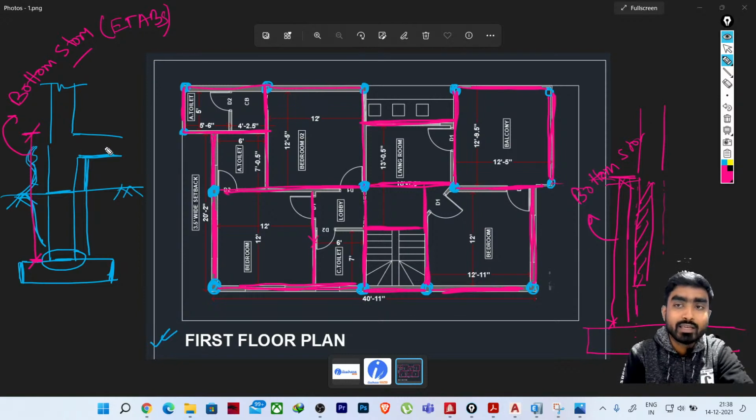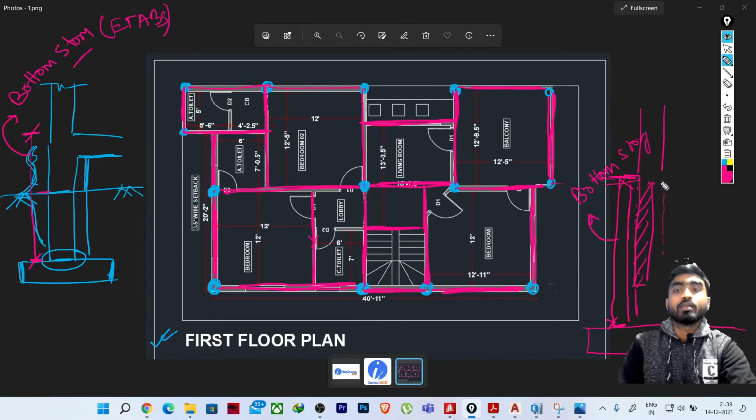This is a similar thing you can see from here, top of the ground level to bottom of the foundation. So it's the same thing we are considering. The only concept is the last story we need to consider as the bottom story. If you are considering from ground floor to plinth level, or ground floor to maybe first floor, it is not the real case. In the plinth level also you will be having these tie beams or the plinth beams, right? So in that case, obviously the effective length of the column will be changing in certain directions, maybe in 2 directions also. So you need to take care of this thing. I think this is very clear to all of you.